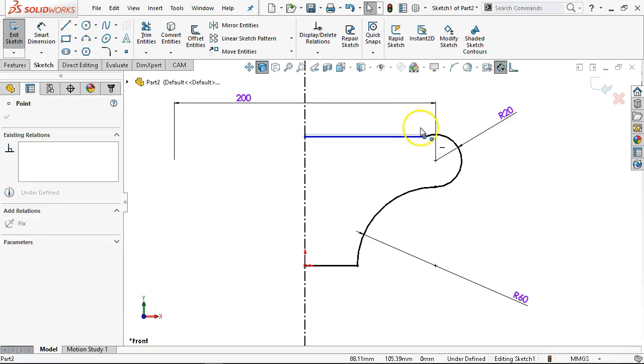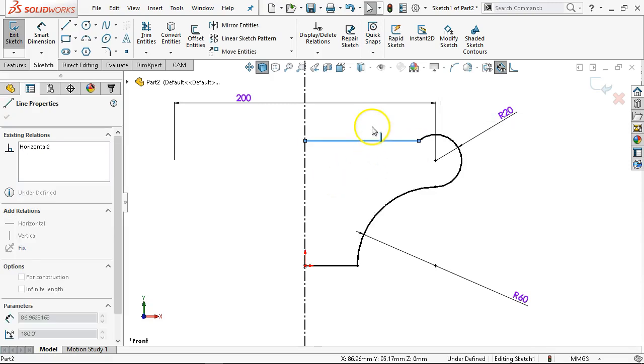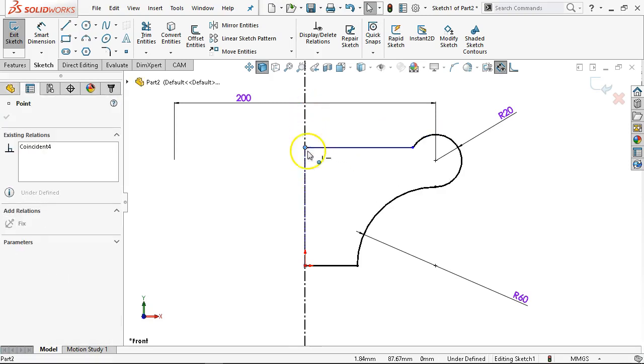and the infamous, I did not get tangency. It looked really close to tangency, but it was not tangency. All right, so that whole pick something that is blue and drag. This is where the diagnostic tool comes into play. If I can move that, okay, and it's in blue, so I know I can move it somehow. I may not be able to move the line, or only be able to move the line a little bit. The endpoints are sometimes a better selection, sometimes the object is a better selection. But it being that close to tangent, but not quite tangent, that's a fairly common occurrence.